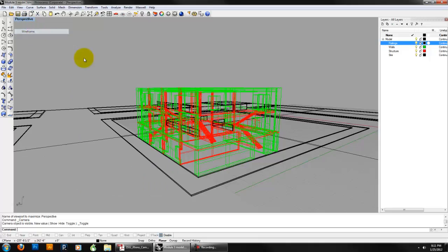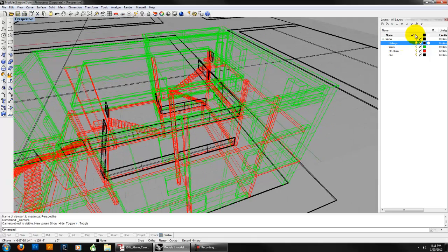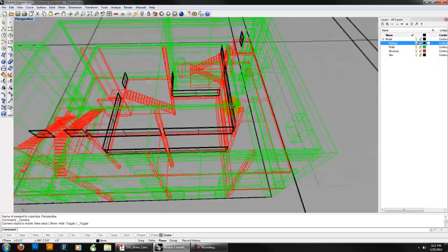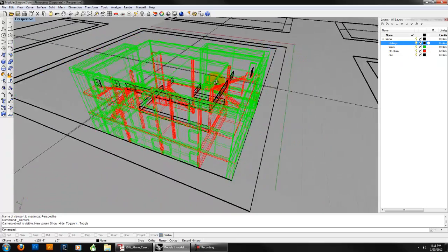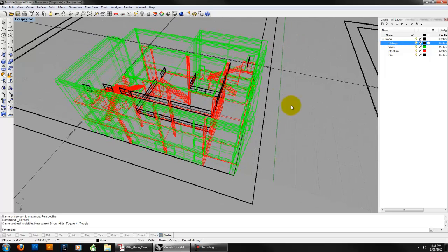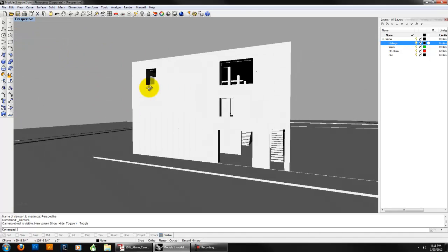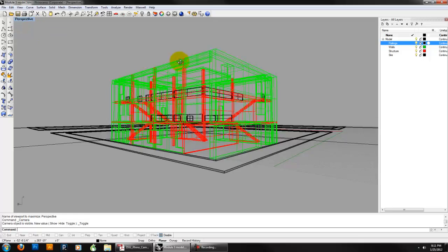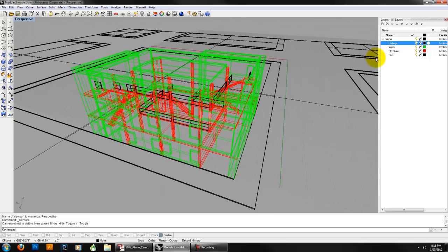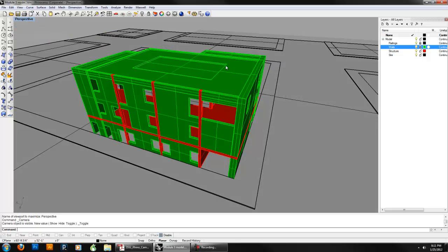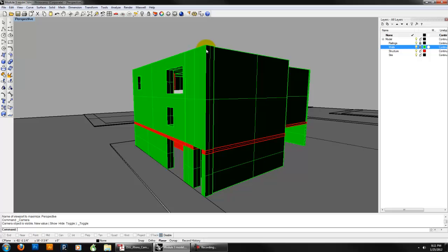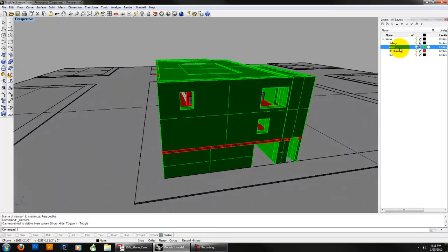You can also change your camera to a wireframe, and you notice that each layer has a different color, and that's purely just a function of the way you have the file set up. They're not actually materials that have those different colors. Okay, they're actually all the color gray. So anyway, this is a helpful way to think about your model. You can lock a layer, which is a way to prevent you from accidentally selecting something on that layer. So if you see it in shaded, actually, I can't pick anything on that green layer, because I have it locked. So that's really useful to do.